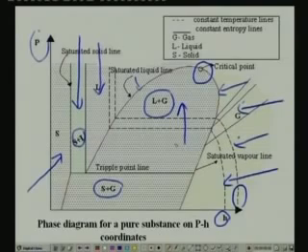And physically, when the working fluid exists below the critical point, you can distinguish liquid and gas. That means if you have collected this liquid and gas mixture in, let's say, a glass beaker, then a meniscus forms between the liquid and gas phases. Whereas if the working fluid is above the critical point, you cannot make any distinction between liquid and gas, and that region is known as the supercritical region.